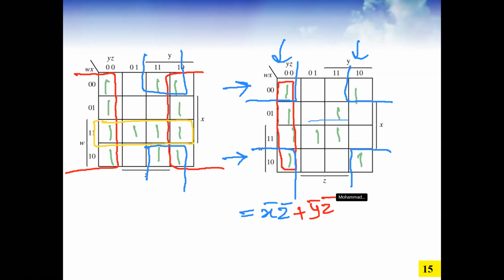Now, what is remaining? Cover them as well. So 3 ones are there. We have to combine them. Row 2 and row 3, it's very simple. Combine this group and combine this group. Done. Clear? Yes. All right. So this is the way you can simplify them. So how many prime implicants are there? 4.